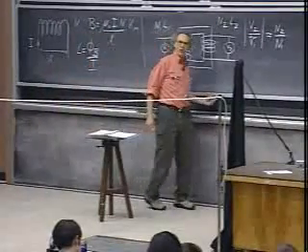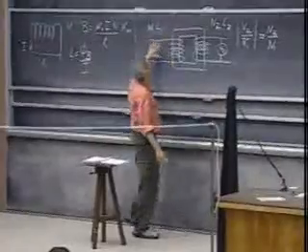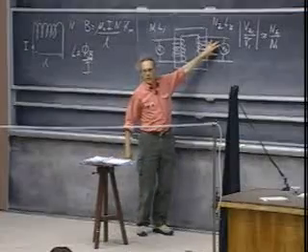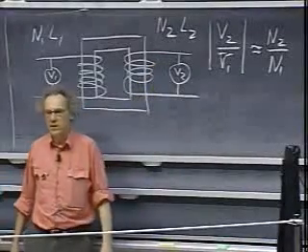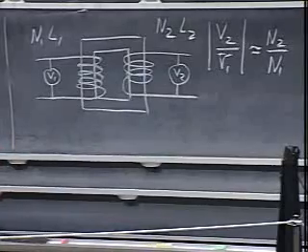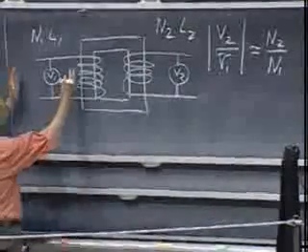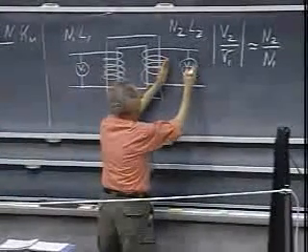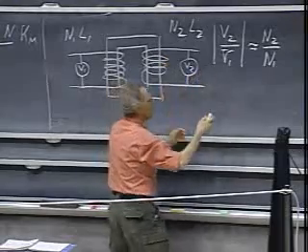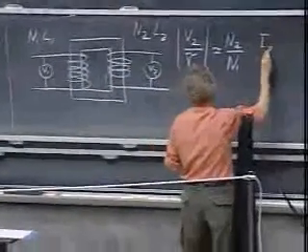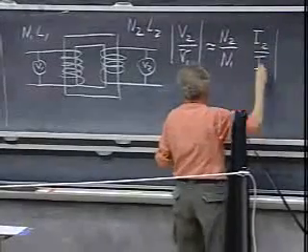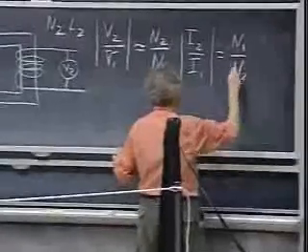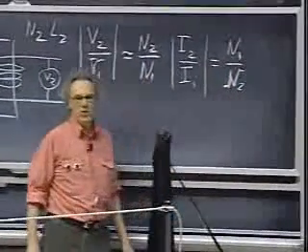Under very special conditions, will the power generated on the primary side be all consumed, 100% or nearly 100%, on the secondary side? That is very, very special. If that's the case, then the time averaged power here, V1 I1, is the same as V2 I2 here, time averaged. And so as a logical consequence of that, you'll find that I2 divided by I1, let's not worry about minus signs, is N1 divided by N2. That, however, is not so easy as you may think.